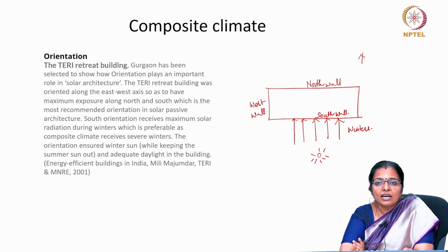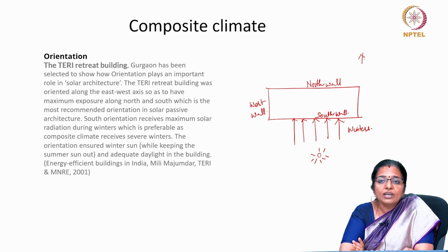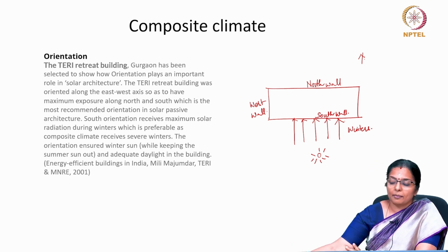These buildings are of rectangular form as this is the ideal orientation, with their longer axis towards the north-south direction. Greater the perimeter to area ratio, greater is the heat gain in the building, unless you are making an attempt to bring in the heat from outside to inside through certain surfaces.